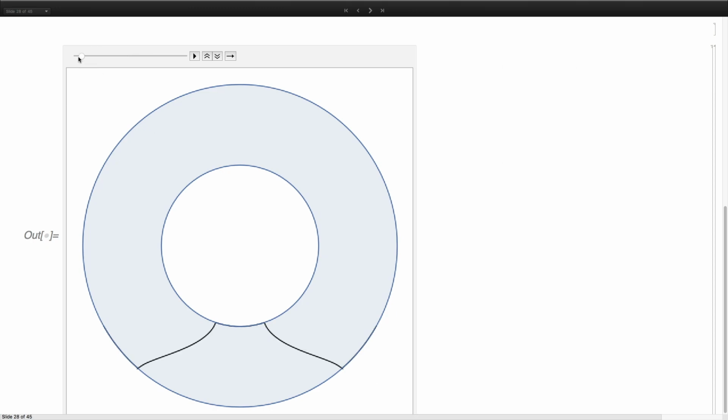The customer wanted to model an annulus that has two different liquids with different density. That's the initial distribution of the liquid, and they wanted to know how this liquid is going to behave in the field of gravity. So we'll look at that. That's how the liquid is going out and flattening out. That's a nonlinear problem, and that's something you can do with the finite element method now.